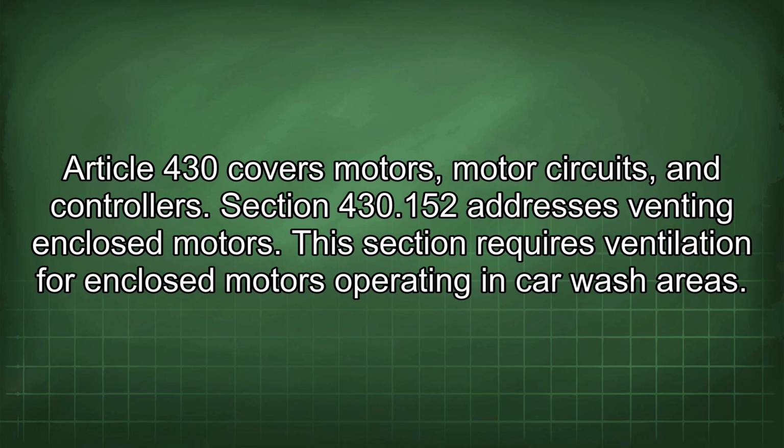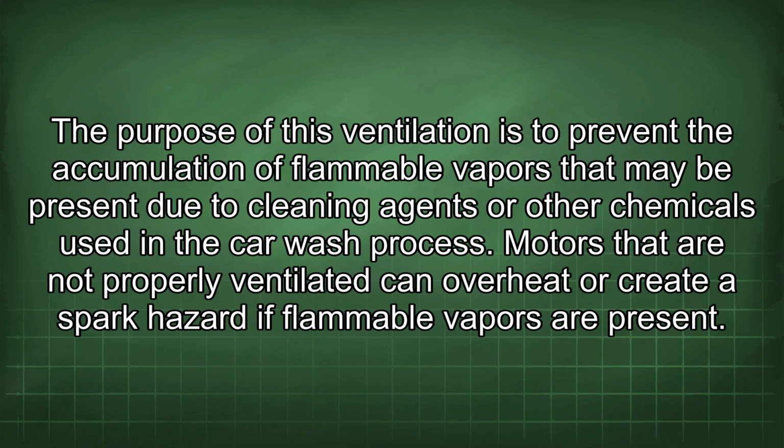This section requires ventilation for enclosed motors operating in car wash areas. The purpose of this ventilation is to prevent the accumulation of flammable vapors that may be present due to cleaning agents or other chemicals used in the car wash process.